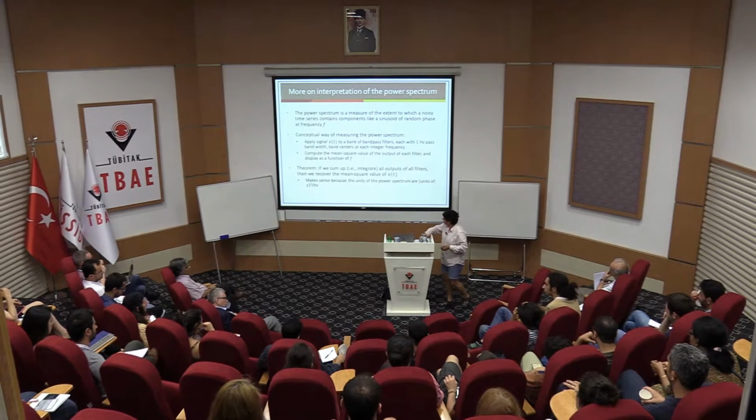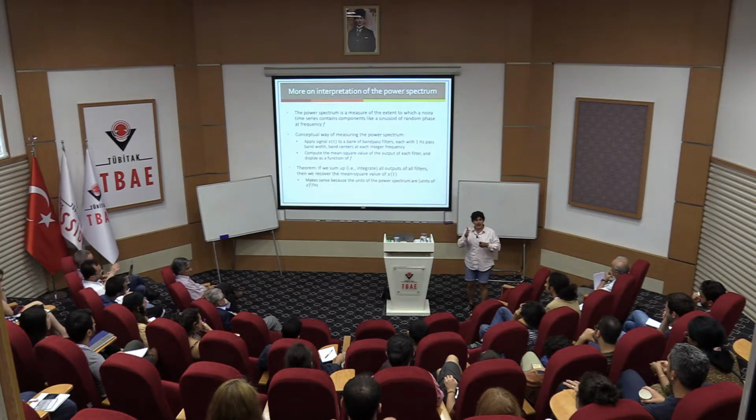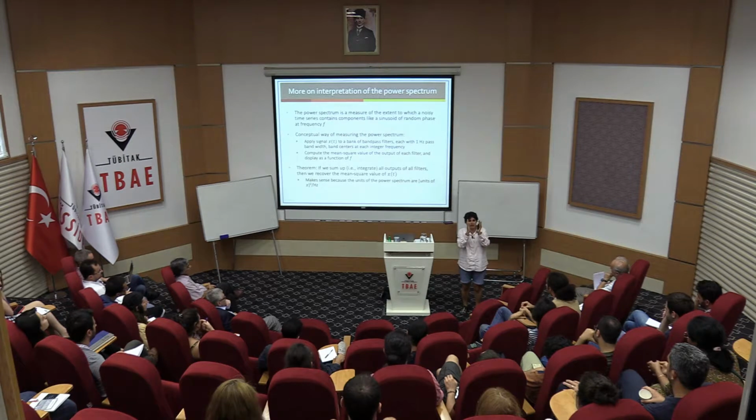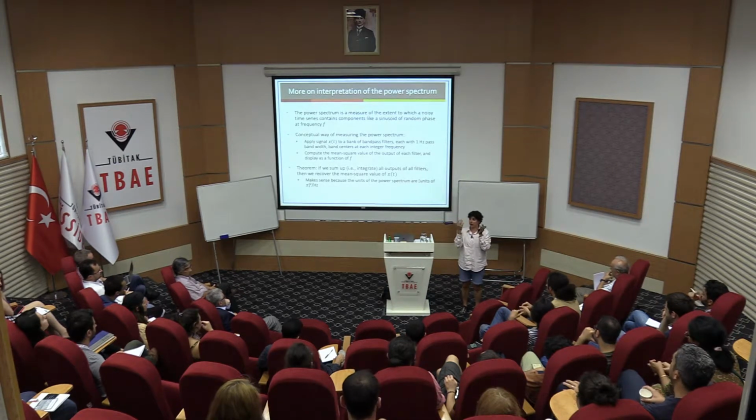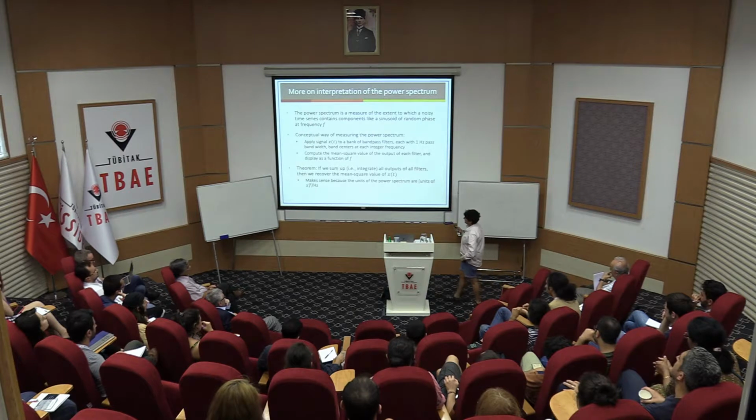Basically a Fourier transform is nothing but a series of filters. And so that's the other thing I want to add. The way that you could actually measure a power spectrum is you could take your time series x of t and pass it through a bank of filters. Basically you could slice it up into, if you were really crazy, 1 Hertz band pass filters, and it would tell you in each of those filter outputs how much energy there is. How much power that is. That's the name. So it's a very important experimental tool.